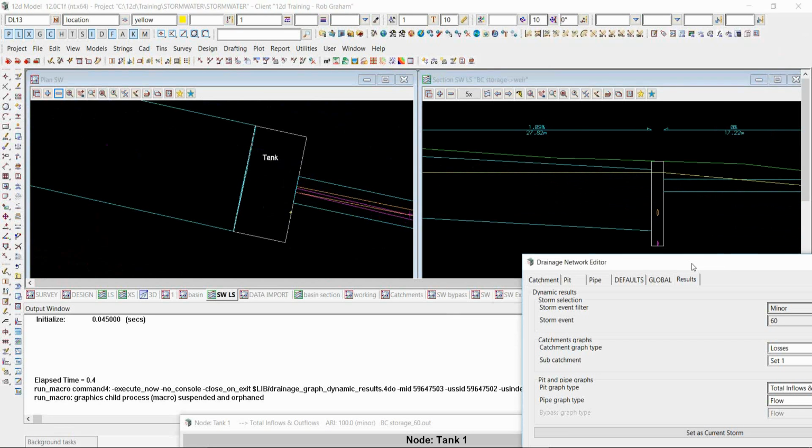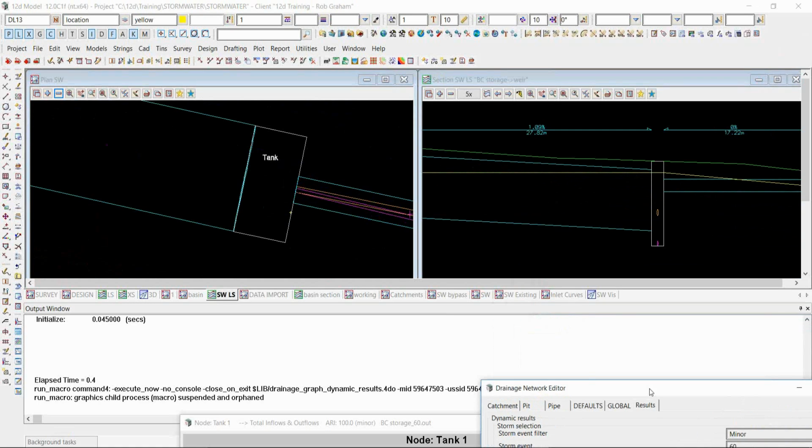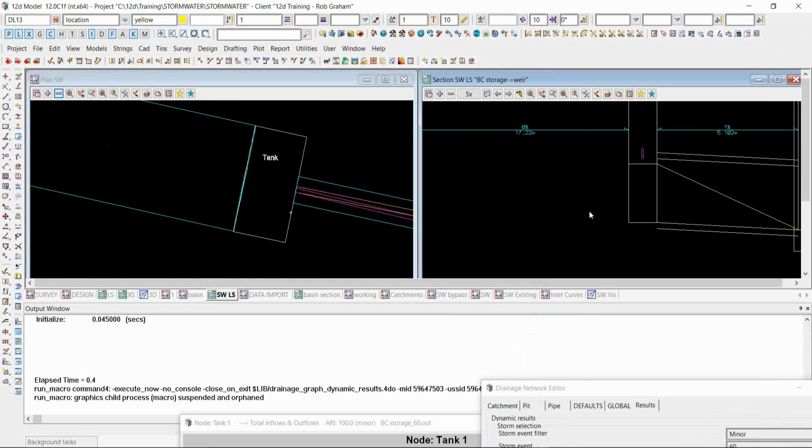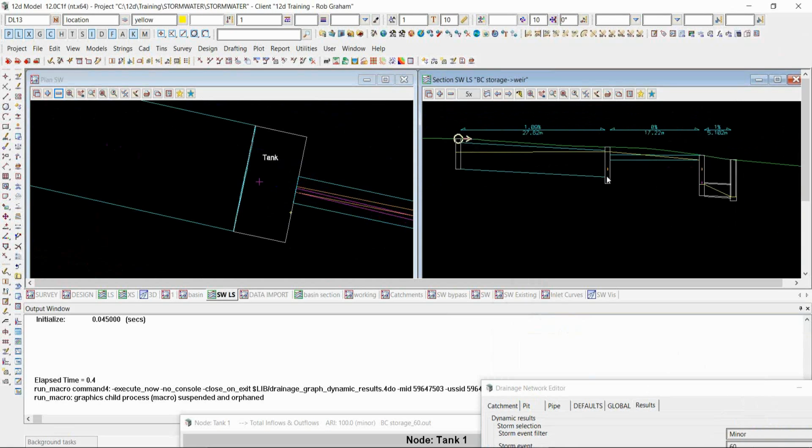Okay. Yep. High early discharge is a term that describes a whole variety of structures. When I first started the presentation, my very first concern was about high early discharge. And the very first thing I did on the high early discharge was I made sure that my tailwater was below my orifice so I could get rid of the water as quickly as I could.